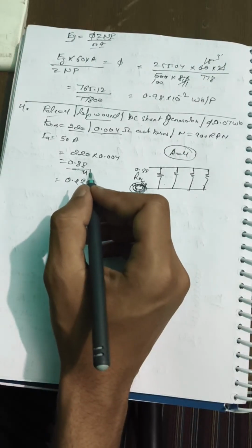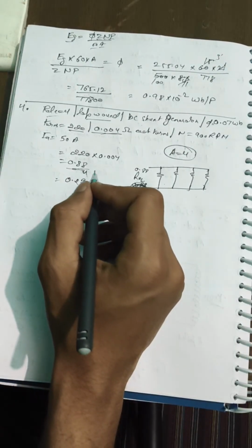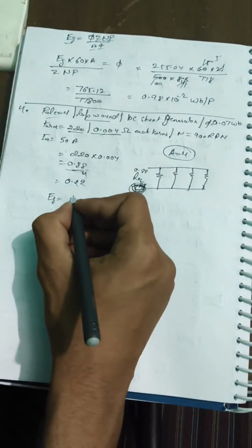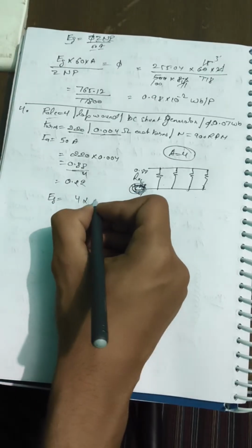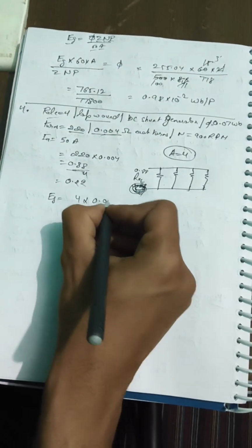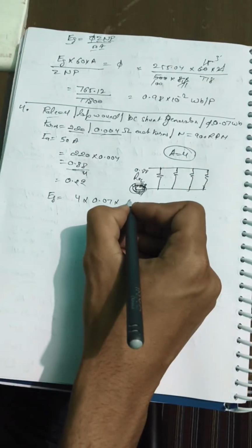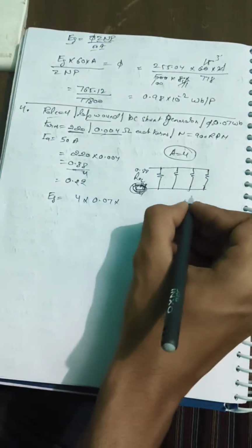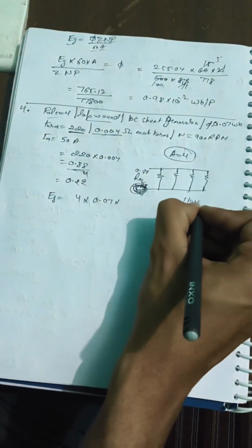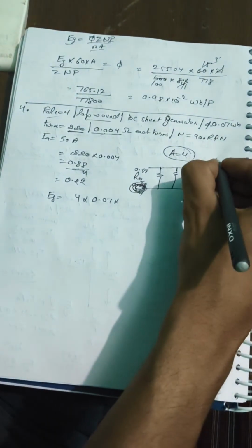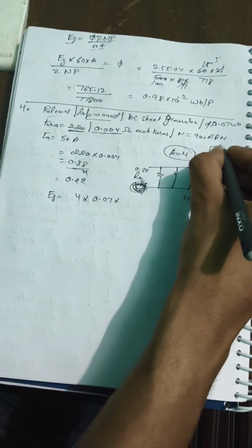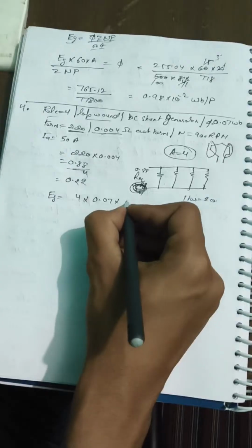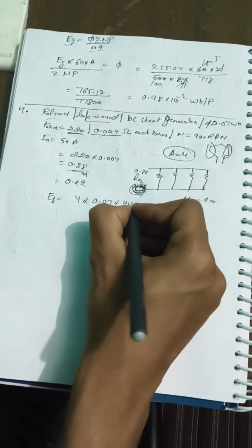Now firstly find the EMF generated, which is equal to number of poles into useful flux into the number of conductors. There are 220 turns and each turn has two conductors, one turn, two conductors. Say this is a turn, it will go that side, the one conductor, the second conductor. So it is equal to 440.